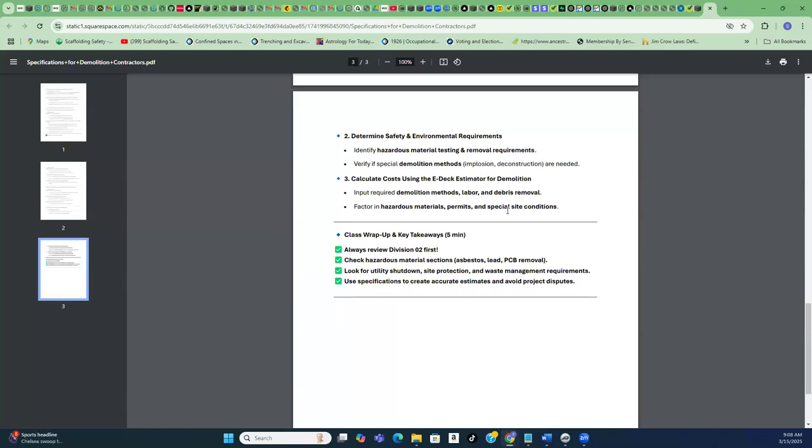Look, like I say, Plan Swift is a ruler. It's a glorified ruler, okay? An accounting tool. That's all it does. And for you, you'll use three things. The counting tool: how many lights I got to demo? Click, click, click, click, click, click. Or how many linear feet of wall do I have to demo? So use the segment tool.